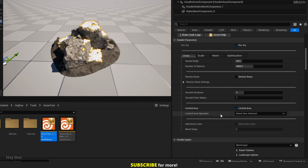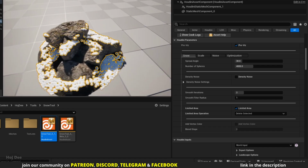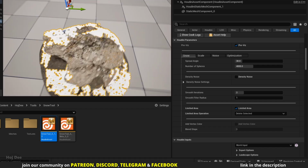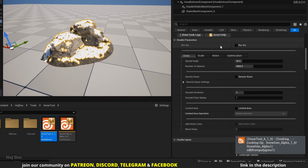The limited area operation parameter gives us the option to either delete the selected area or the non-selected area. By default, it deletes the non-selected area, so we only have the snow in the areas we have defined, but we can set it to delete selected too. This way we'll reverse it and remove the snow from the areas we have defined. So let's disable the limited area and the previous options and continue.